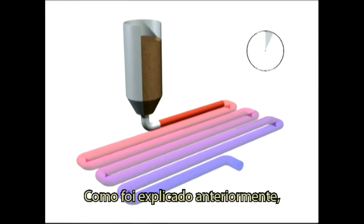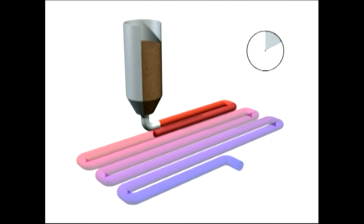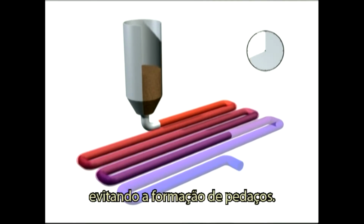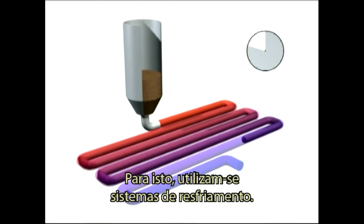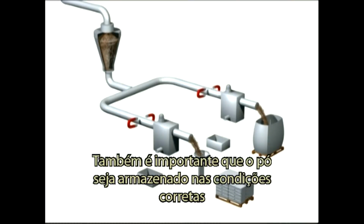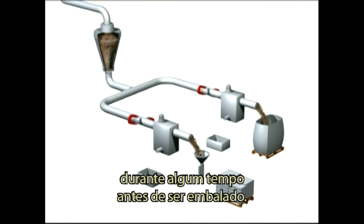As explained earlier, there is still cocoa butter in the cake, at a minimum level of 10%. It's very important to allow the butter to crystallize in a stable form, thus preventing the formation of lumps. To achieve this, cooling systems are used. It's also important that the powder is stored under the correct conditions for some time before packaging.